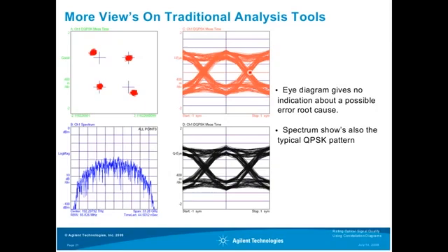And if you see this kind of distortion, you can directly go to the bias voltages of this Mach-Zehnder interferometer and optimize your transmitter to have a perfect constellation and 90 degrees as it should be between the I and the Q path of the signal. So the quadrature error describes the deviation from orthogonality of the I and the Q modulation.